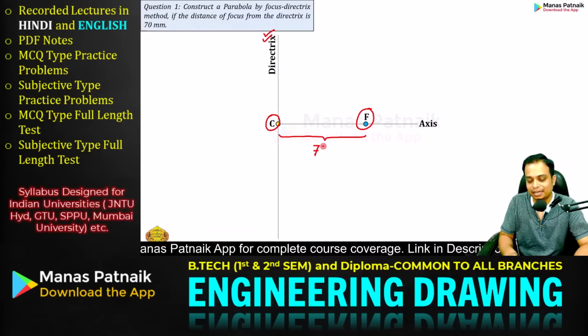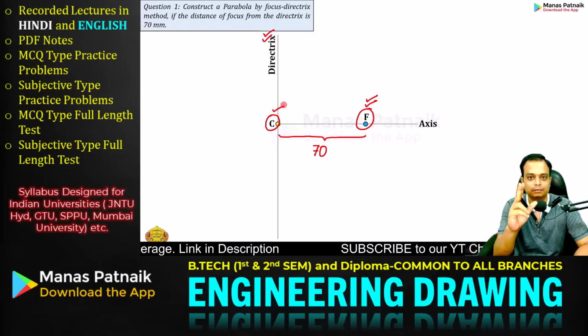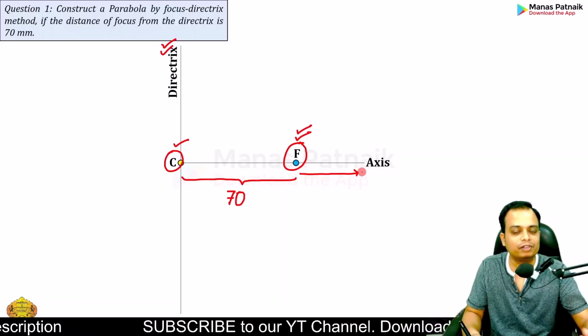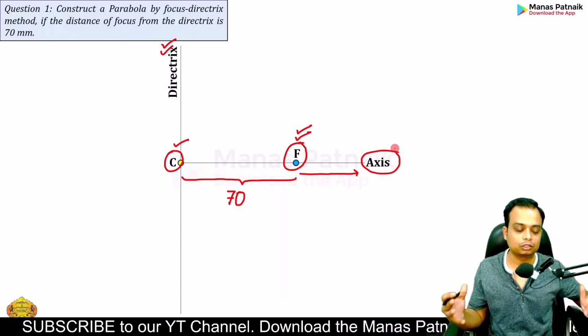This has to be taken as 70 millimeters. It's very simple. On this horizontal line, you need to make a point over here at a distance of 70 millimeters from C. That is your first thing to do, and you can then extend this line by 40 or 50 millimeters. By the way, this line is your default axis of the parabola.